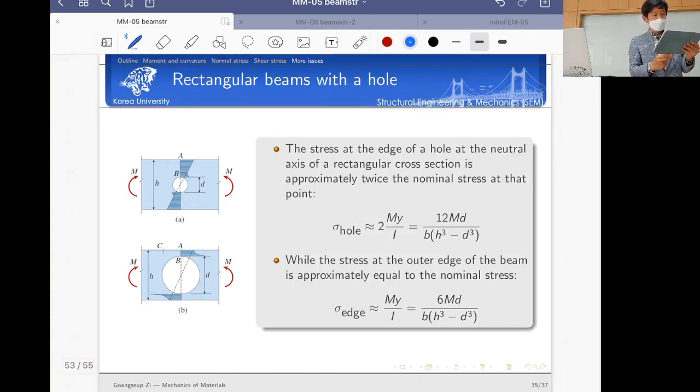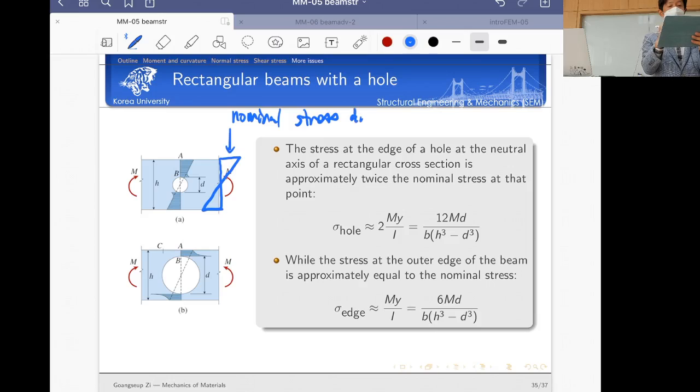Okay. All right, so now let's talk about stress concentration. So far, when we discuss the beam problem, look at this. Let's say we calculate the stress field here. There is no hole. If there is no hole, my stress field would look like this, okay? We call this nominal stress distribution, so-called 공칭 응력 분포. Nominal means we don't care about what happened inside, okay? We want to check the overall stuff. I don't care about what happened inside.